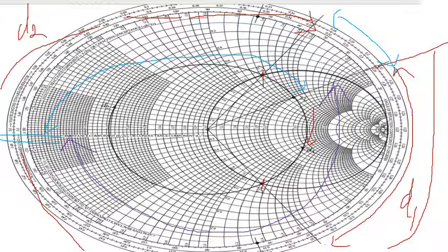I just have to add the remaining part as 0.174 lambda. What is the 0.174 lambda? The remaining part. Meaning, I'm taking the purple line again, so I'm just going to add that to this. So the total D2 will be the addition of 0.5 minus the position of the ZL point, subtract from there and add the new existing Y2 point. So totally you will get the answer as 0.405.